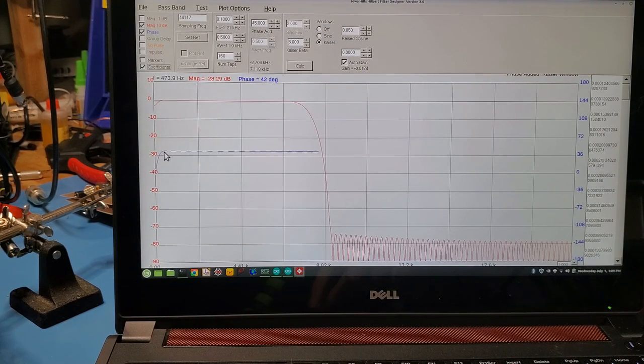That phase relationship starts to deviate from the 45 degrees that we want. So we got 45 degrees roughly here. Down here, you can see that phase relationship starts to change. So down low, below, let's say 400 hertz, that filter is no longer performing its job.